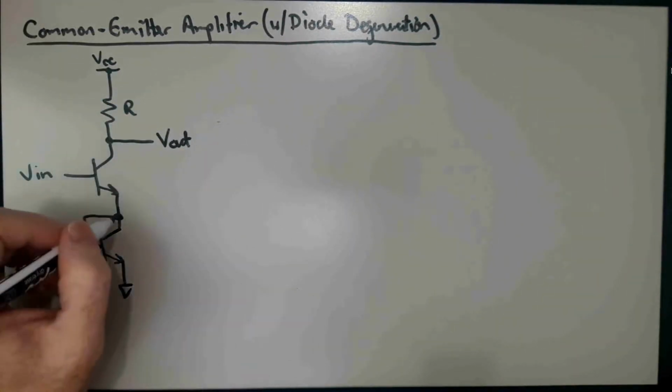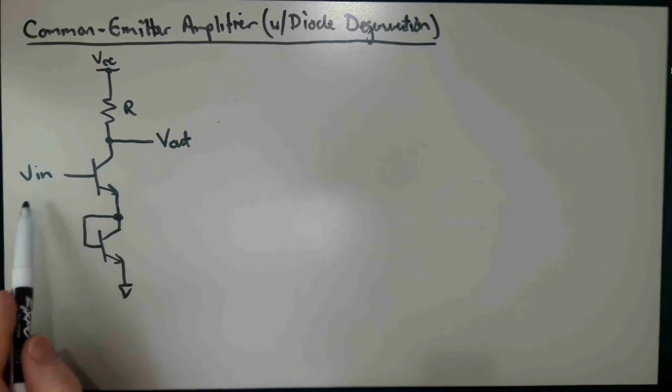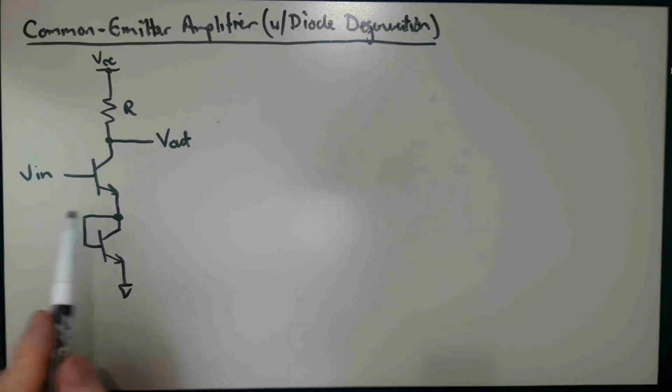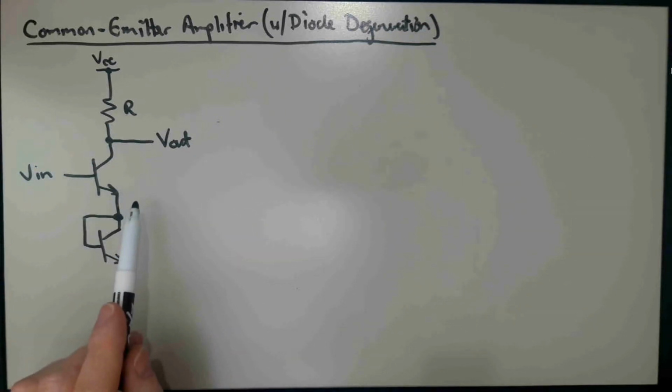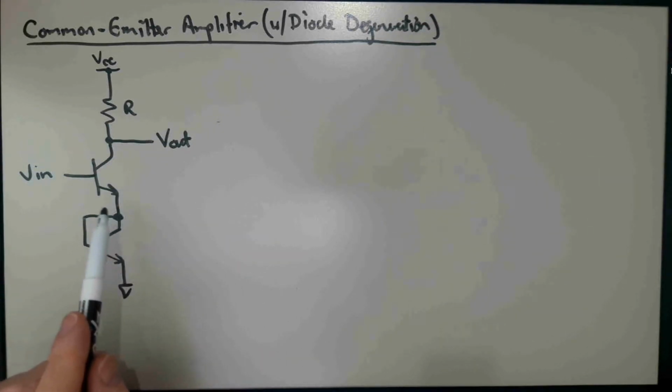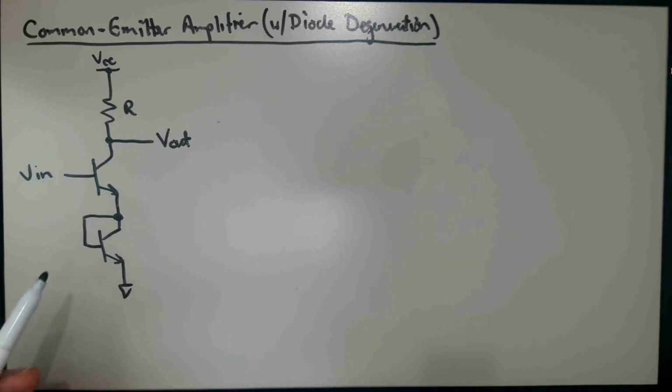And our goal with this is going to be to find the voltage transfer characteristic and to find the incremental gain of the circuit, which is dV out over dV in, using direct differentiation of the voltage transfer characteristic, and this will be a large signal analysis. And we're going to go back and also look at what's called a small signal or incremental analysis and try to correlate the results of these two analyses.